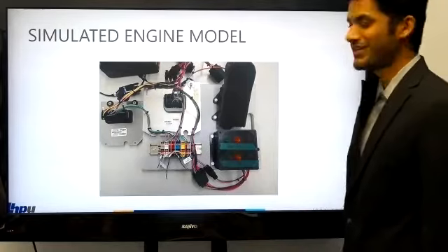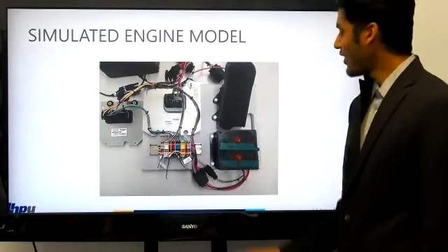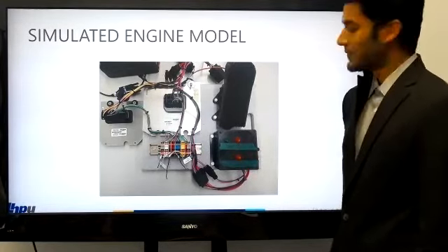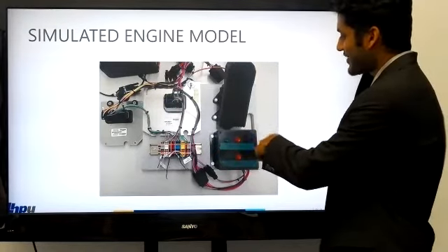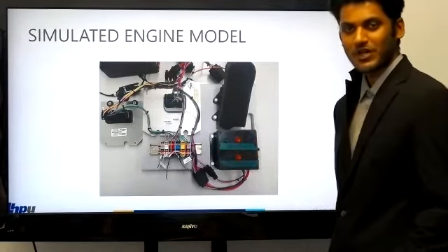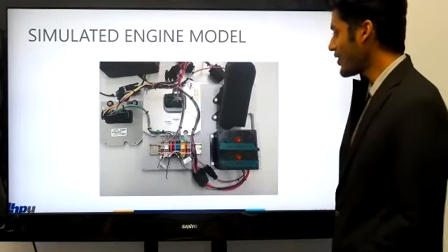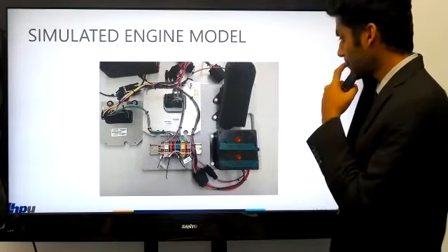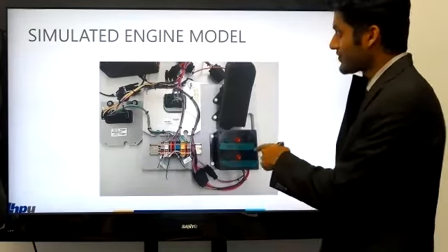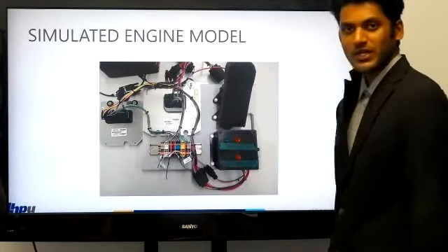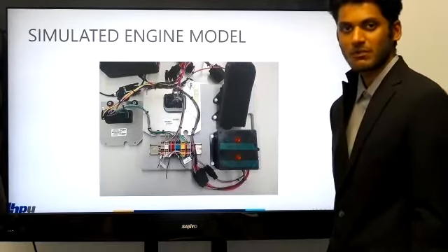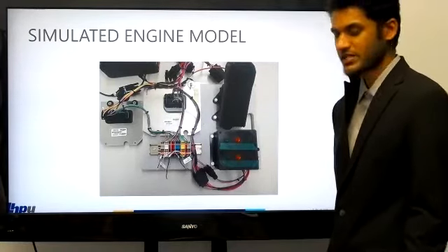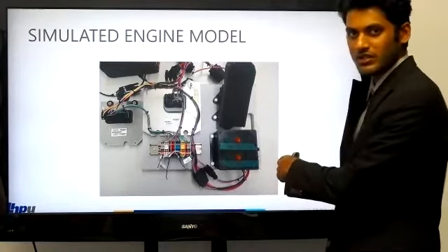At first, when we ran the HIL model, all of our engine lights were on. The first 5 lights were there because we sent the wrong CAN messages. The engine uses a 29-bit extended CAN identifier, but we gave this message format as standard, which should have been extended. This resolved this problem.